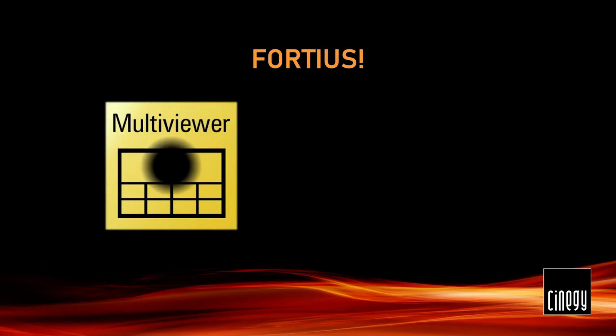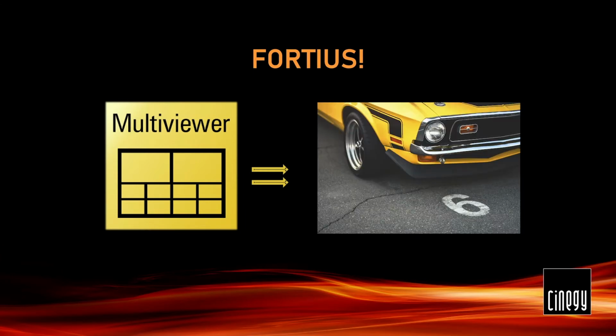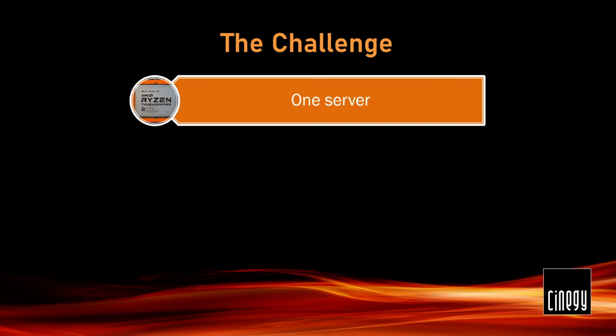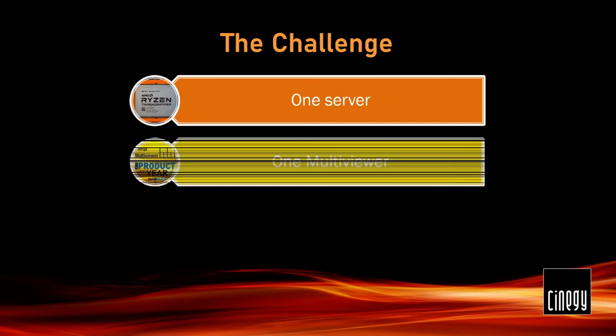We've been using NVDEC to decode IP feeds as well as NVENC to encode the IP outputs ever since version 11. But recently we have made significant improvements in Multiviewer's GPU pipeline, and this is mainly what this video is going to be about. Bored by the lovely pleasures of year 2020, we challenged ourselves to build a high-density multiviewer server able to decode and display an impressive 100 full HD feeds.